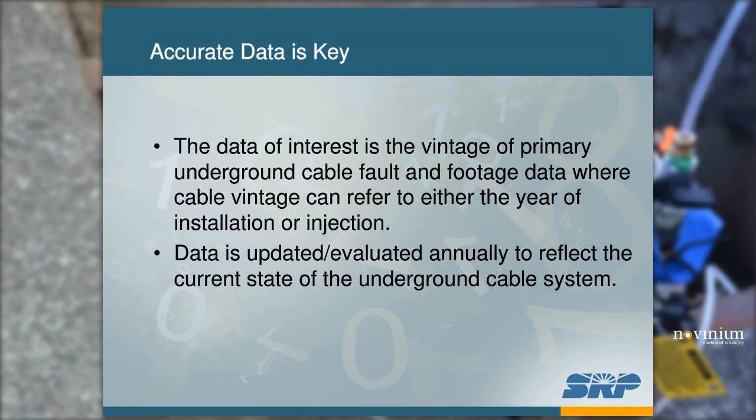First thing I'd like to talk about is data. Data is the foundation to this program. Without it, you can't do anything. The data that is of interest to us is primary cable vintage data, where the vintage refers to the year of installation of the cable or the year of injection of that cable. So in terms of faults and footage, that's the data we're after. Faults and footage based upon the year of installation or the year of injection for that particular piece of cable.